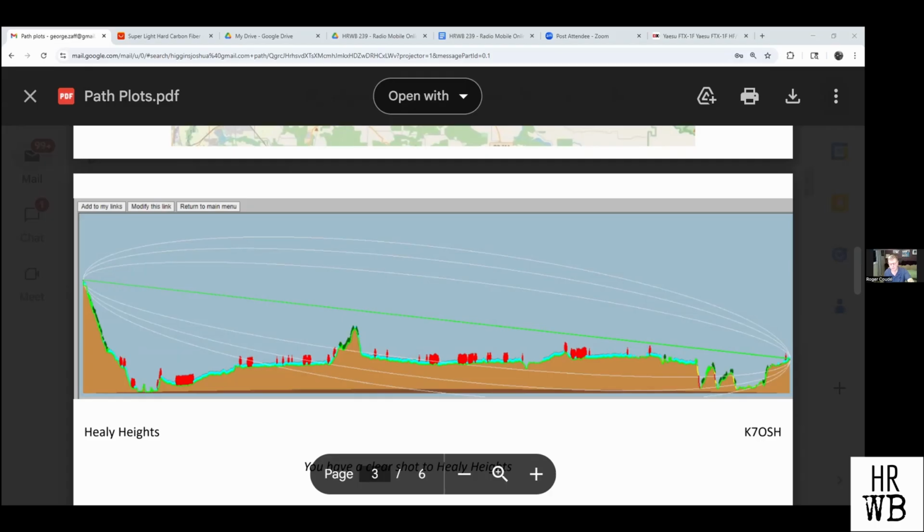So if you take the first Fresnel zone clearance to the white line, you take 0.6 of that and you try to adjust the obstruction to fit that 0.6. So in your case, I will increase the antenna on the right until I have 0.6 where you have this obstruction. You see there is a little. Yes.